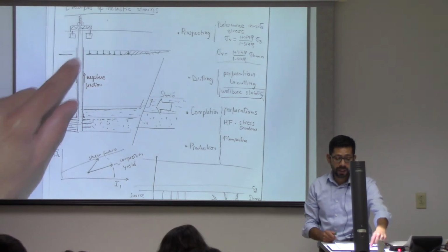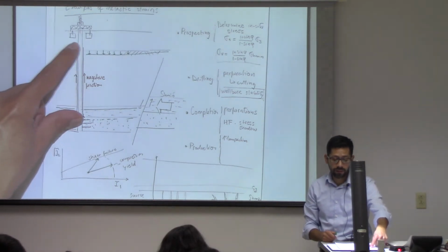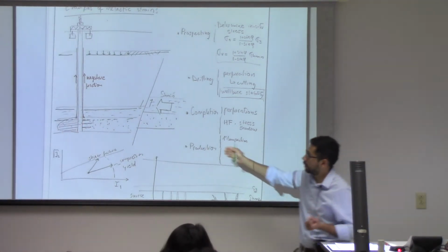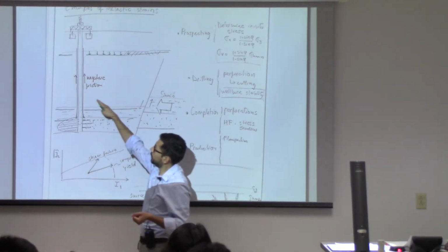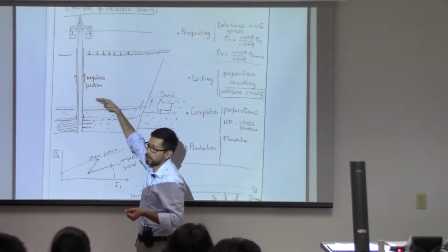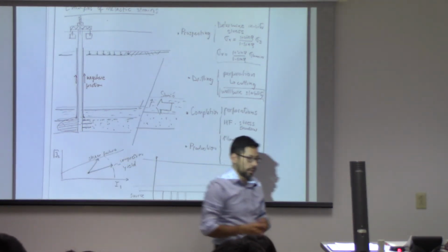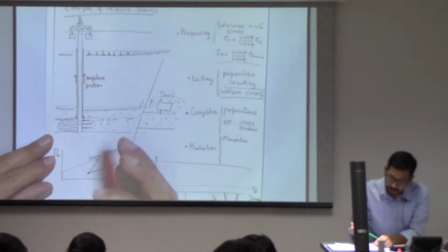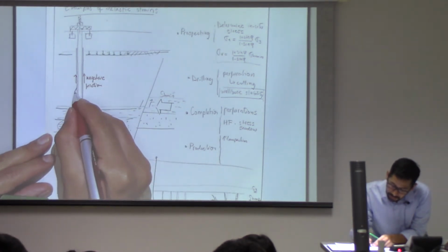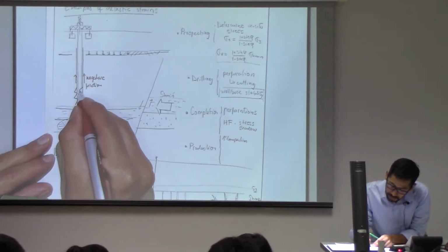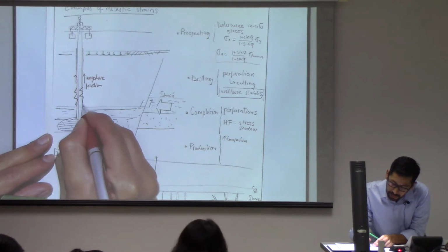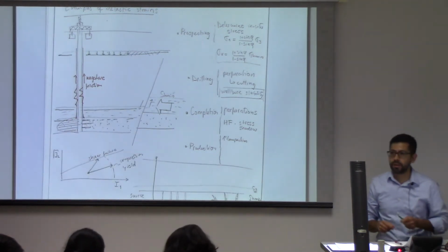So sometimes you can put so much force, because now all the rock and the semi is going down and is hanging by friction on the casing. What that can produce is casing failure. So your casing may buckle in compression.